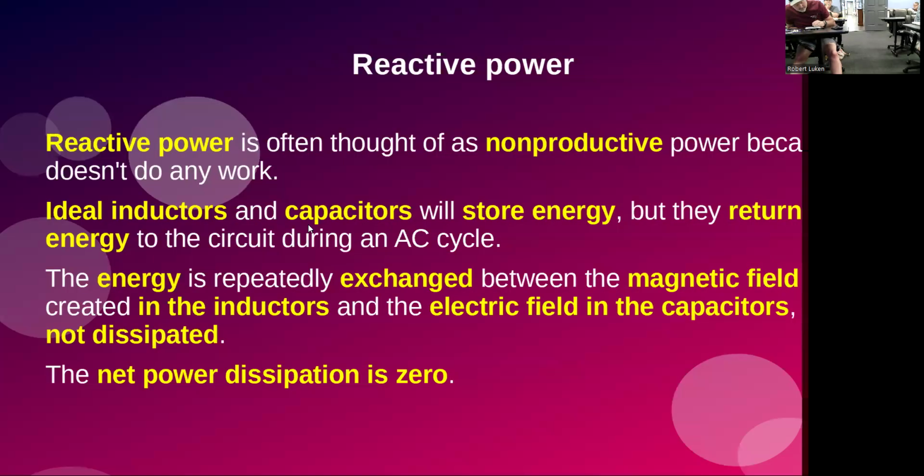And we'll have another one coming up showing reactive power. And they say it's non-productive because it is actually imaginary. It doesn't do any work because you're charging inductors and capacitors, so the energy is just going back and forth. So in theory, there's no loss or no dissipation.